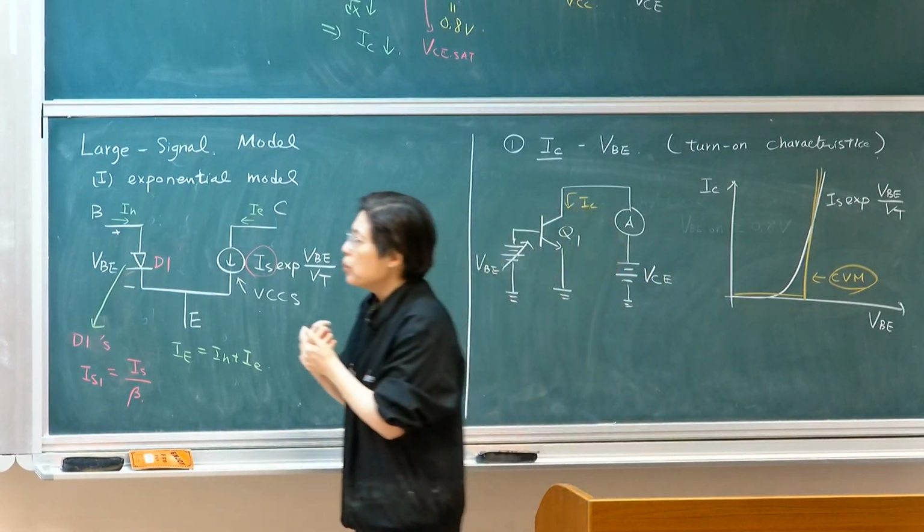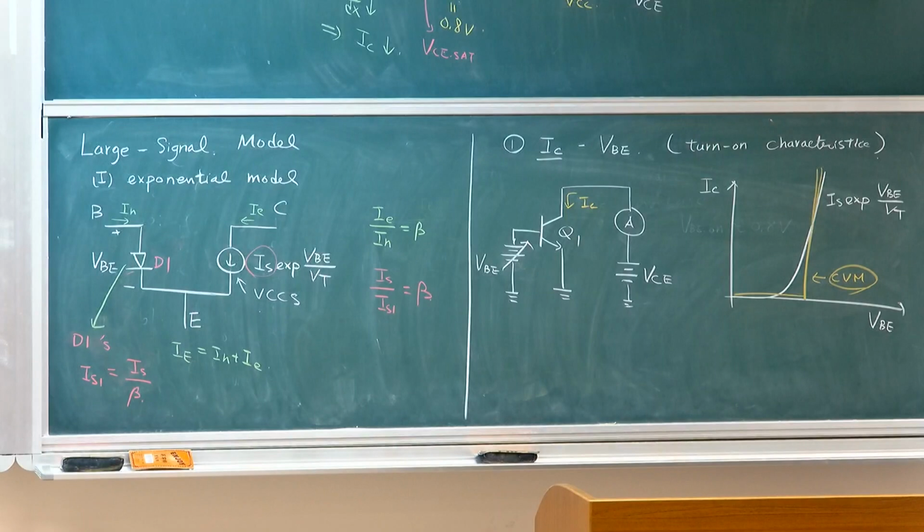So what we're going to do, the more interesting part, as I said, is a circuit where rather than having just the DC bias, because we're doing amplification, the idea is that you want to have your signal, which is the modulating component, being amplified. To analyze that, we need to establish something called a small signal model, the same as the diode. So how do you generate a small signal model for an NPN transistor?